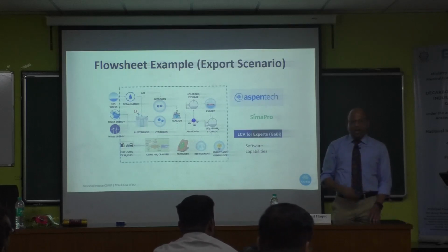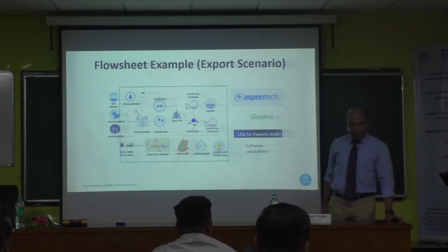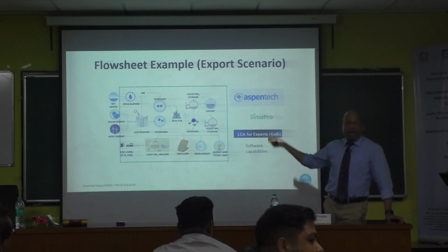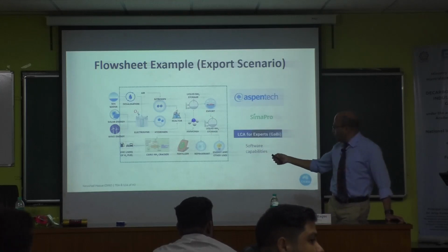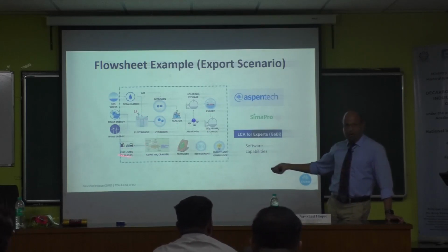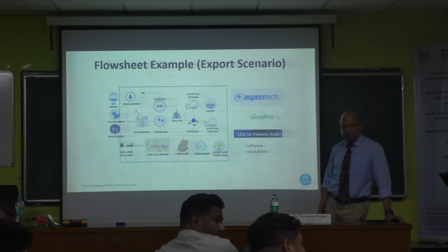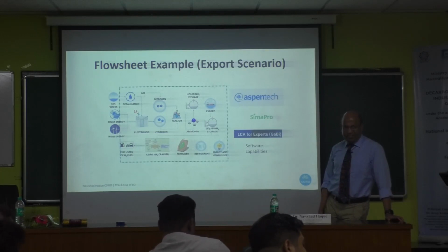Yes. So now tell me, from the skilled colleagues here, what do you think is the biggest challenge for this sort of hydrogen application? If I want to produce steel using that hydrogen, and it goes to a steel plant, what's the problem? The problem is the present blast furnace technology is not compatible with using hydrogen. That's the first thing, because we cannot put hydrogen directly into the blast furnace like that. The technology has to change completely.